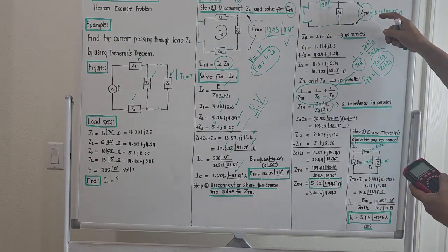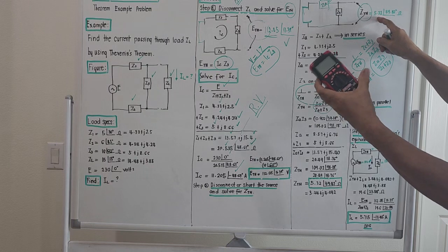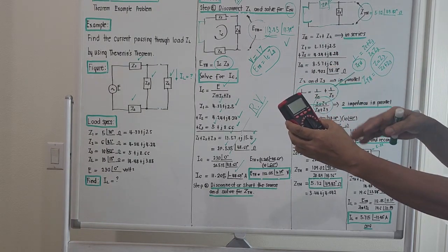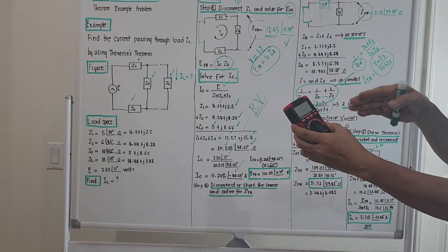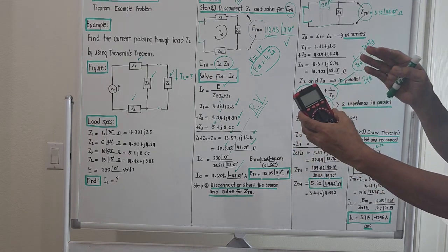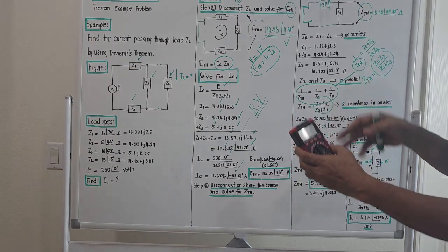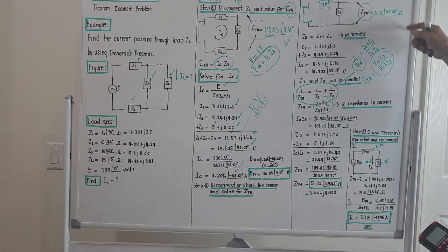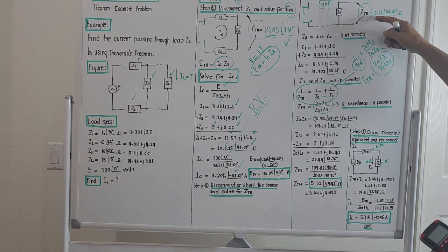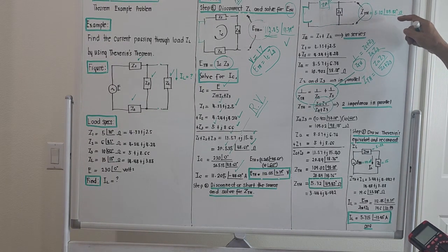So the open circuit impedance across this, in case we use an impedance meter, what will come out should be 5.32 magnitude. By using the impedance meter, we cannot just use the multimeter. Better use an exclusive impedance meter for measuring impedance value. But theoretically, what comes out for the open circuit impedance is 5.32 angle 49.42 degrees.